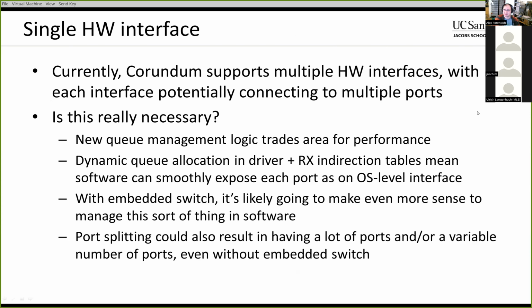Right. So that's that. And then the other thing that I've been mulling over is moving towards using a single hardware interface, where we remove all of the duplicate descriptor and completion handling logic that's currently associated with the quote-unquote interface, the mqnic_interface.v file. Instead of having multiple of those, we just have one, and then software can split things accordingly and manage the resources. I think this is going to be better from a scalability standpoint, and also on some of the smaller FPGA boards. There is potentially a question of things like packet rate if we have more sharing, and what that might do.